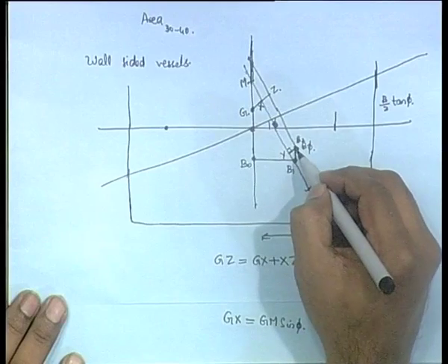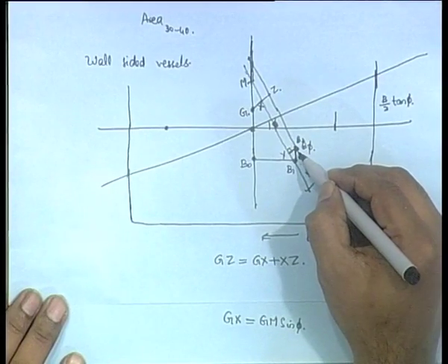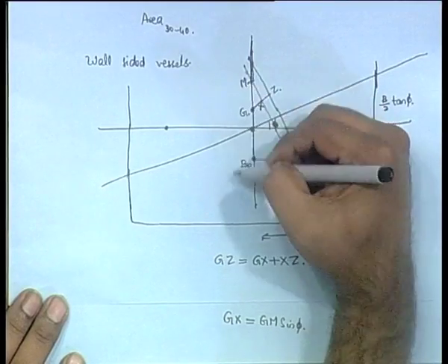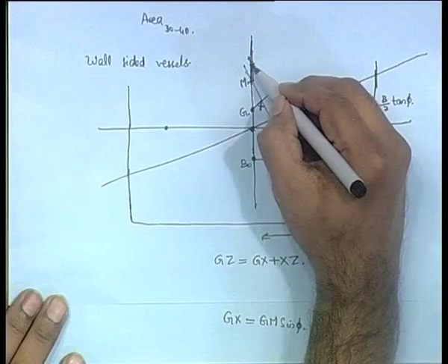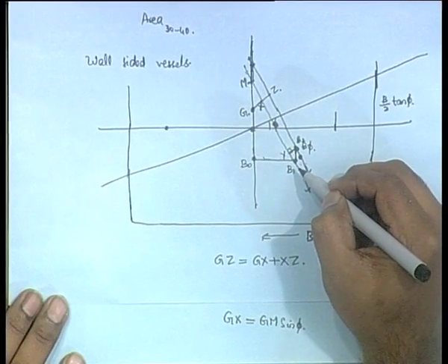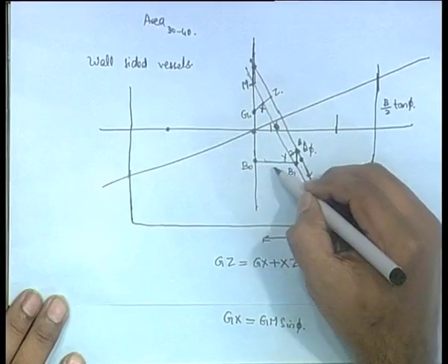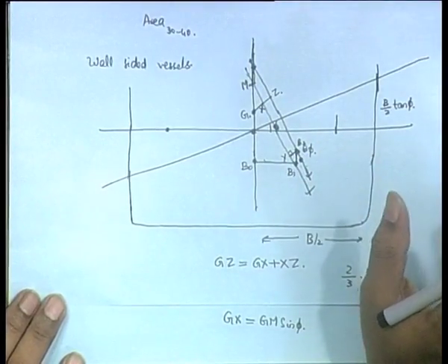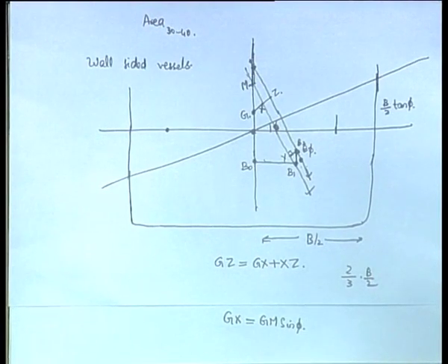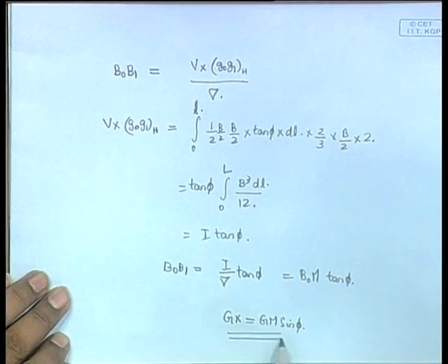So, you will never hear anywhere in naval architecture that when you draw a vertical at B phi, where it hits the original vertical, that is called m. It should have been here actually, but it is not there. It is actually only the horizontal movement of B that matters in the position of m. The vertical movement of B is so small compared to the horizontal movement, we never bother about it, that is all. But you should know this. So, you get Gx is equal to Gm sin phi, that is one detailed expression.